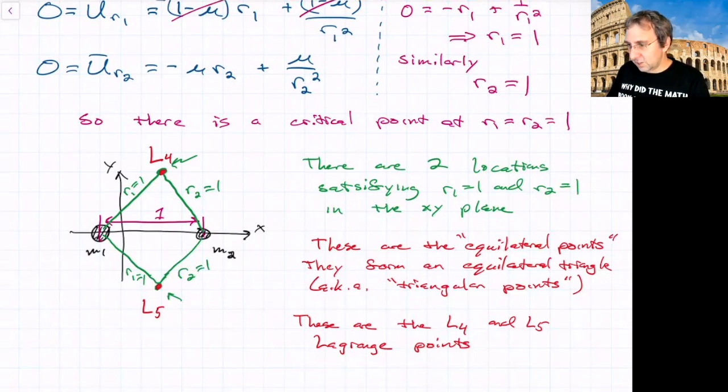So you get a linear system. In this case, if this is 6 dimensions, 3 position, 3 velocity, we would get a 6x6 square matrix. And based on properties of that matrix, looking at eigenvalues, you could determine the stability type of the equilibrium points. And these will turn out to be stable equilibrium points for most values of mu found in the solar system. If the mass ratio gets too large, those points actually become unstable. And that's kind of interesting.